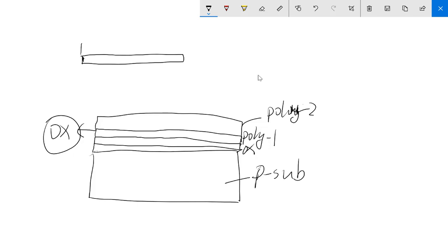And if you make a certain area over here using the P2 layer, and then you do another layer underneath the oxide layer using the P1 layer, there will be a common area in between. It's like two metal plates which has a dielectric material in the middle. You cannot adjust this. This is fixed, right?